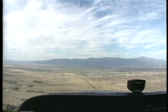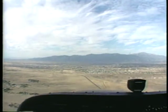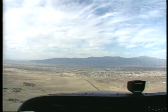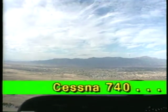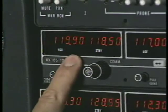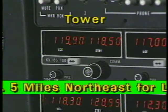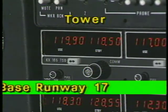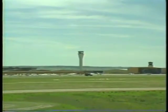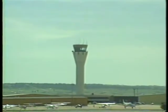As you near the airport, approach control will let you know when or where to contact the tower. Cessna 740, 5 miles northeast of Jensen, contact the tower 119.9. Cessna 740, tower on 119.9. Jensen Tower, Cessna 62740, 5 miles northeast for left base runway 17. At airports with an operating control tower, you must obtain a clearance to land. Cessna 740, cleared to land, runway 17.